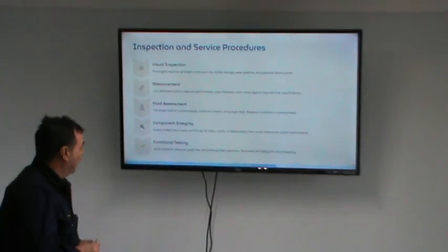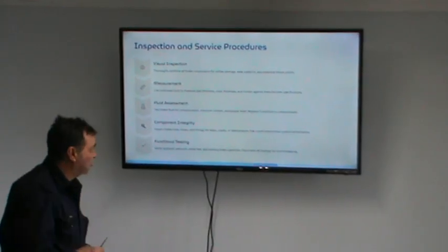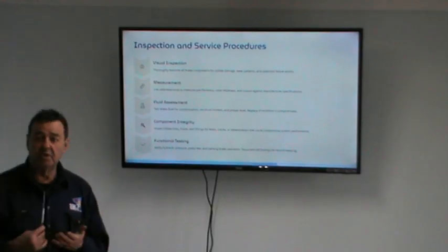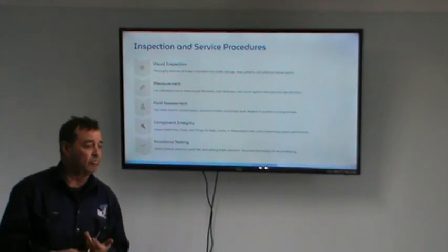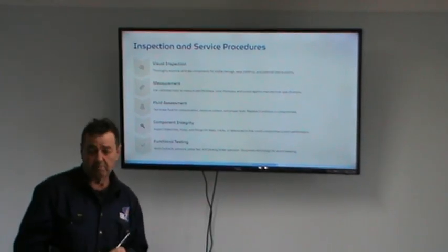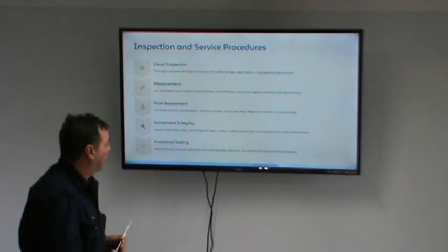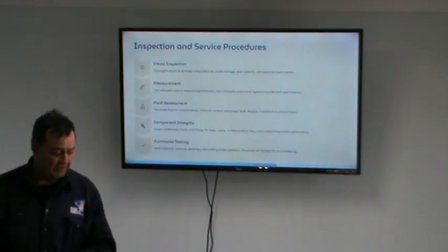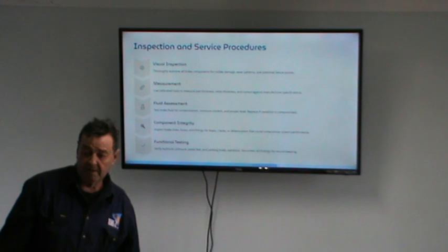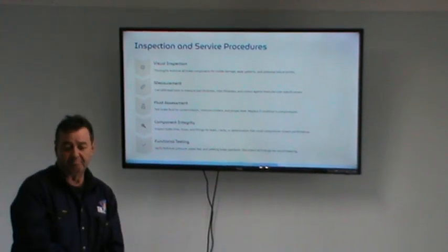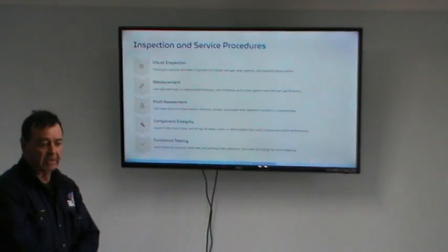measurement. When we're measuring tools, brake pad thickness, rotor thickness, disc run out, lateral run out, parallelism. Here we go, 4-syllable, 5-syllable word. We always got to make sure that we refer to manufacturer's specifications for the minimum and maximum, what limit they can go to.